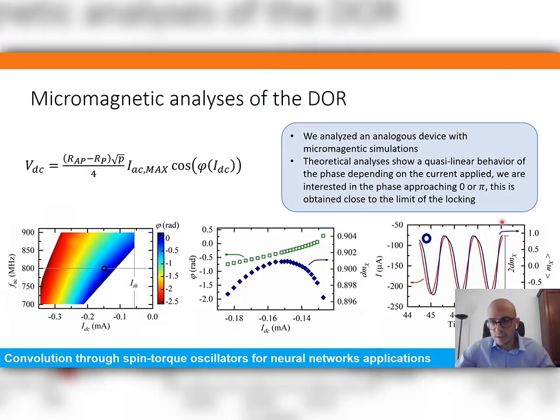From this plot we can have an insight into what the intrinsic phase shift between the two curves is and what the power is, since it scales with the amplitude of the magnetoresistive component. And in order to have a parabolic phenomenon, and in particular the peak of the parabola, we need this phase shift to be close to 0, to pi, or multiples of pi.